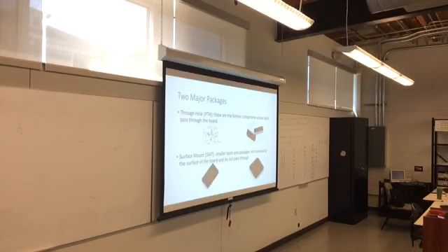Okay. So this is Ashleen's board right here, and you can see this is what gets made out of the PCB design, and there are no holes on here except for these through holes on the side. And those are used for headers because we're debugging this chip. But what she's going to do is she's going to stick this little stencil mask on it, which has the exact same cutout as all these pads. And so she sticks the stencil over top of the board and then takes solder paste and smears it. It'll fall exactly where the pads are. And then you just get some tweezers and put your pins down.